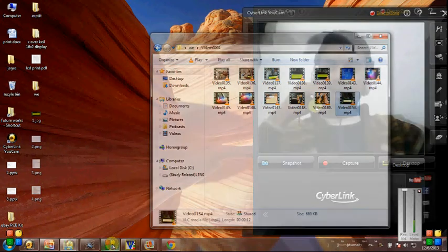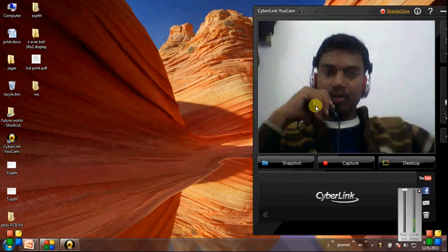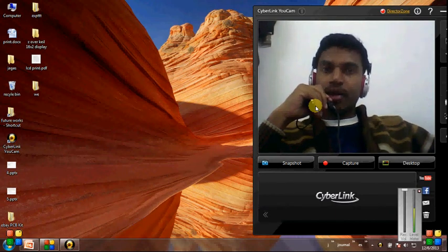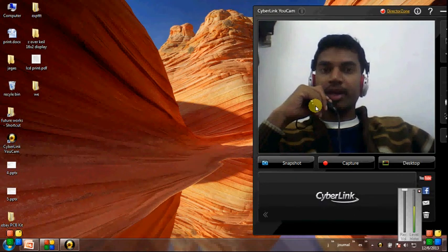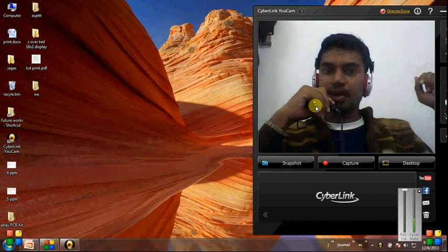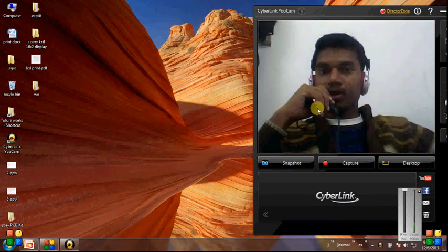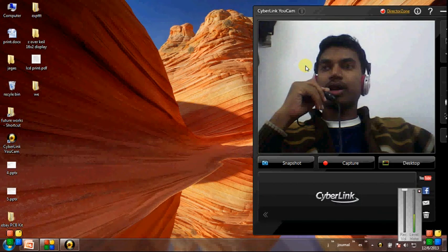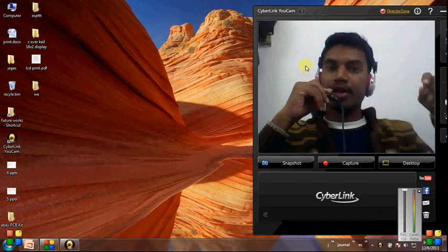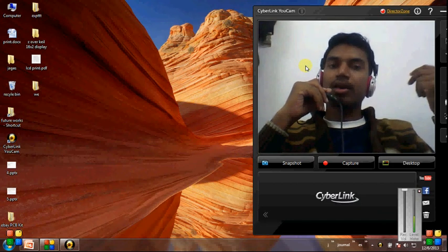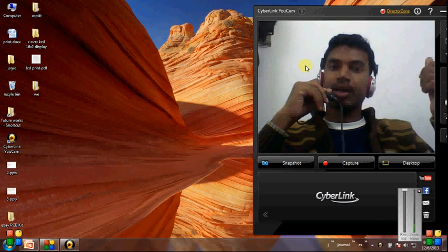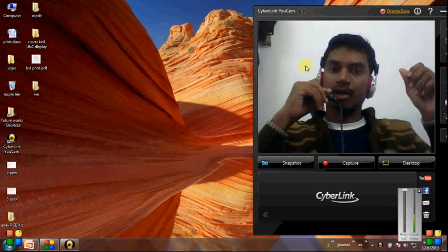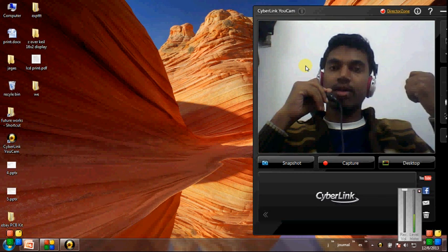That was all about LCDs. I forgot to tell you, if you want to display letter A on the LCD display, then what you have to do is send the ASCII code of A onto the data register by selecting the various control pins. And if you want to write 0 onto the LCD screen, then you have to send the ASCII code of 0 using the data lines and the control lines. So in this way you can control the 16x2 display.